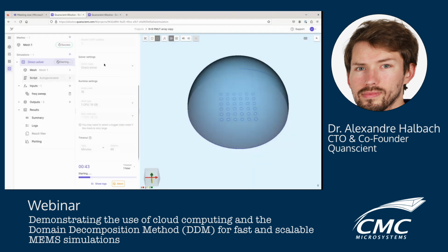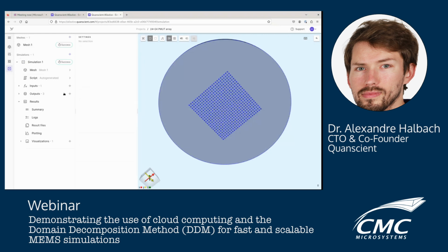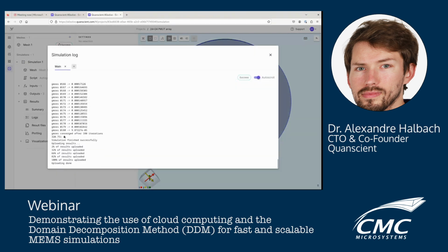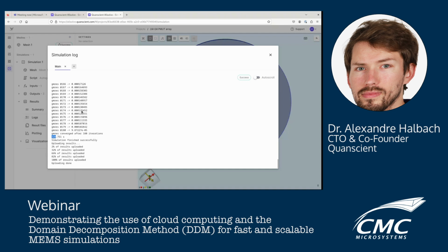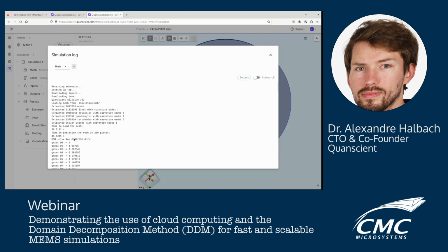And while this is running, I could show at least, because now I won't have the time to run it, what this one has done. So this is a 24x24 PMUT array. I think you remember it was running, it was kind of here when I started the demo, and now it's finished, and it took 320 seconds for the run, a few more tens of seconds to load the mesh, but this was actually 68 million unknowns on 200 nodes of each one core. So this is equivalent to having access to 2 terabytes of RAM.